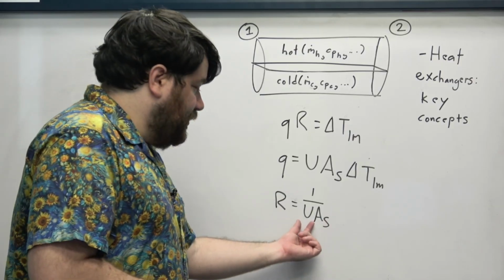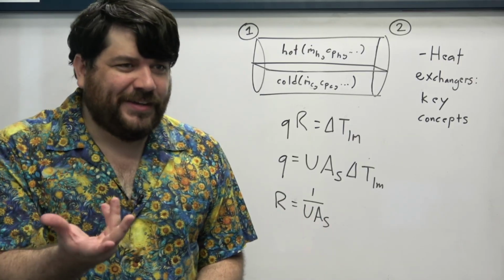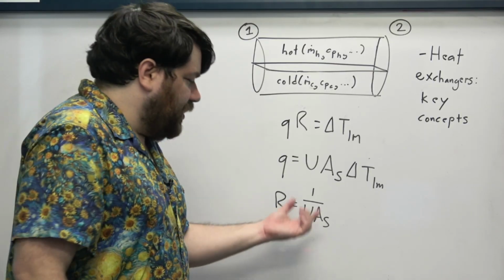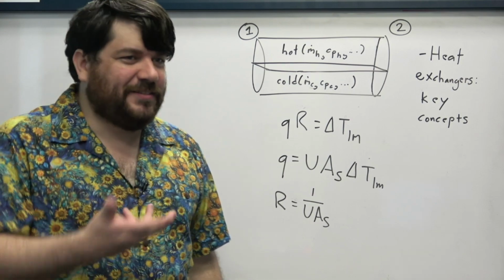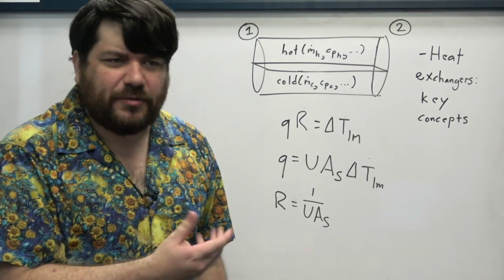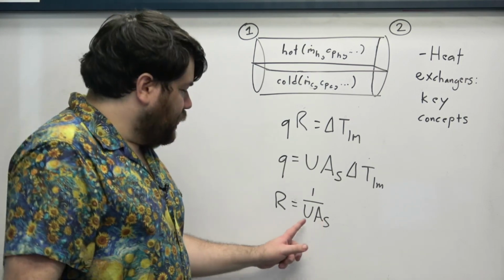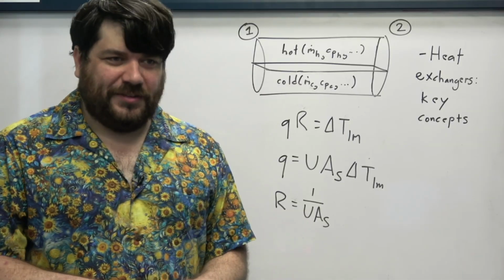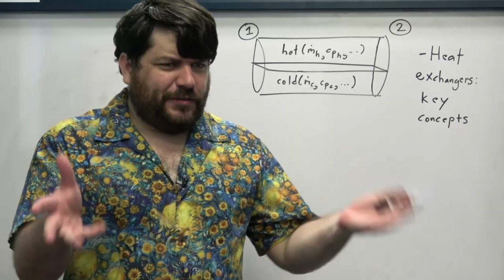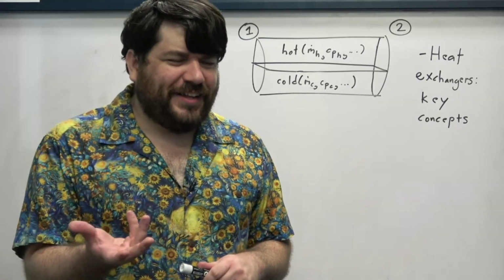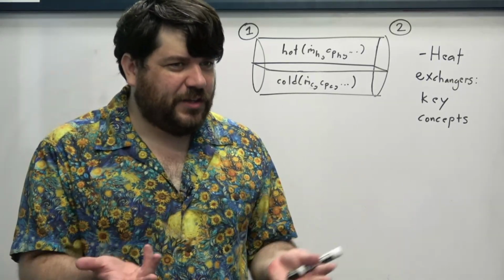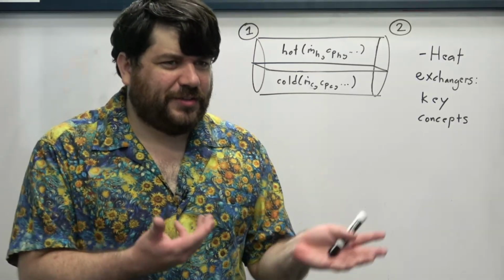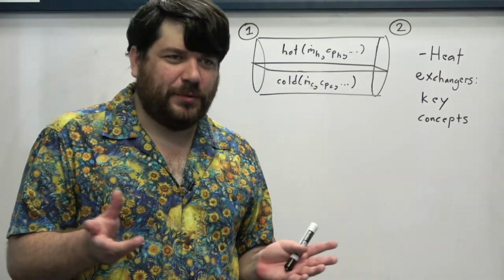And so it has the same units as the standard heat transfer coefficient, all right? Very often when you try to find tables or figures that characterize the behavior of a heat exchanger, you'll usually find this value U listed for them. So we have an equation for calculating, or at least approximating, the Q as a function of either a total thermal resistance or this effective heat transfer coefficient U.